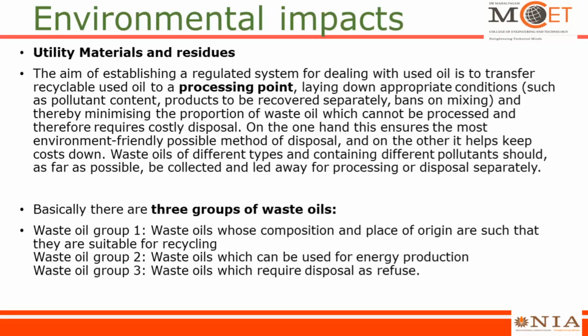Waste oil of different types and containing different pollutants should, as far as possible, be collected and led away for processing or disposal separately. Basically, there are three groups of waste oil. Waste oil group 1 is the waste oil whose composition and place of origin are such that they are suitable for recycling. Waste oil group 2, these oils which can be used for energy production. Waste oil group 3, which require disposal or refuse. Right, so they are classifying oils into different groups based on how they can be utilized after